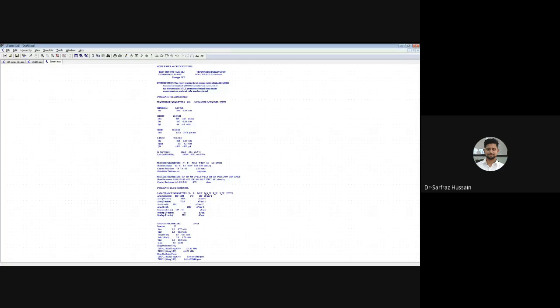So I hope you have learned this. In the differential amplifier that I have shown today, we have just assumed the mu and Cox value. We have not calculated the exact value of the mobility. That is why we are getting a different result in our case, because we have not considered the actual mobility, that is the Kp value or Kn value.